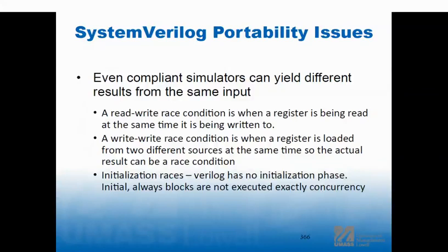You think of gate level simulations as the last thing that you're doing. But I always run gate level simulations early, and we'll talk a lot about that in a few weeks. I find something right off the bat, and it's very frequently an initialization condition. And I think, boy, I wish I had known that sooner. Now, I do a whole bunch of other stuff in gate level sim. We'll talk about what that stuff is. But find the easy stuff early, right? And sometimes just doing the gate level simulation is work, right? Getting the right files in the right places, things like that. So it's good to not be under the gun when you're trying to do that. So remember these race conditions.